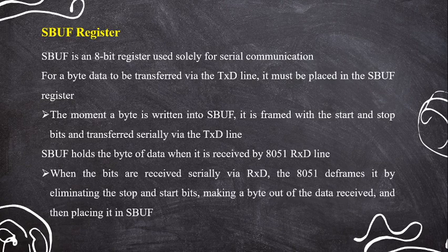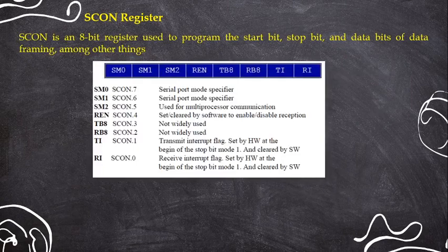When the bits are received serially through the RXD line, that is the receive data line, on receiving the data the start bit is eliminated, the information is copied, and the stop bit is also eliminated. Effectively, what we get is an 8-bit data in the SBUF register.